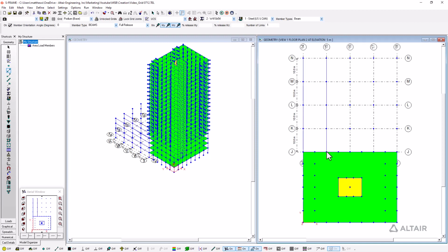And we're going to have these girders connecting to the slab and the column on the concrete tower. And in the other direction, I'm going to actually change section size, so I'm going to go with a smaller section size and just left click and drag around the columns that I want to connect with these types of beams. I'm not going to have a beam running along this edge, however.